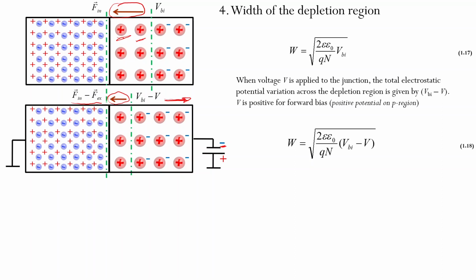are talking about so-called forward bias in the forward direction. When we reduce potential difference, because we have here VBI minus V, minus applied potential difference to these electrodes, as a result we get smaller thickness of the depletion region. So it shrinks, it becomes smaller.